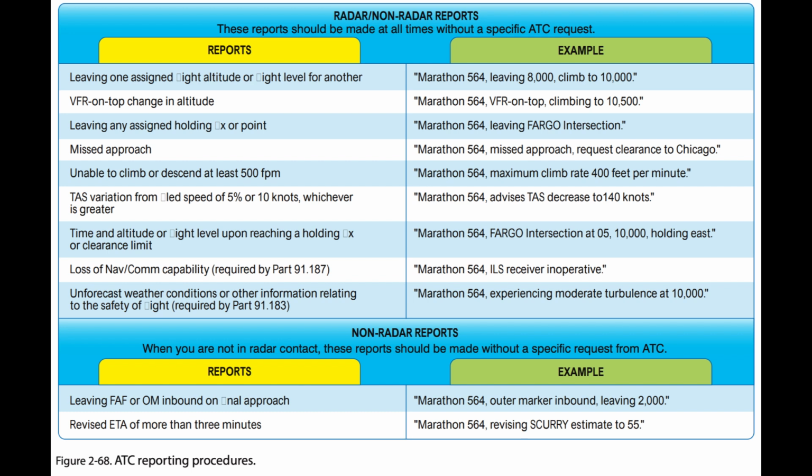If on a direct course that is not on an established airway, report over the fixes used in the flight plan that define the route, since they automatically become compulsory reporting points. Compulsory reporting points also apply when conducting an IFR flight in accordance with a VFR on-top clearance. Whether a route is on an airway or direct, position reports are mandatory in a non-radar environment, and they must include specific information. A typical position report includes information pertaining to aircraft position, expected route, and ETA.